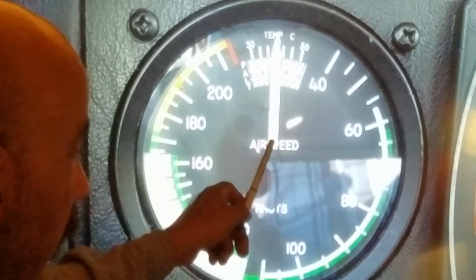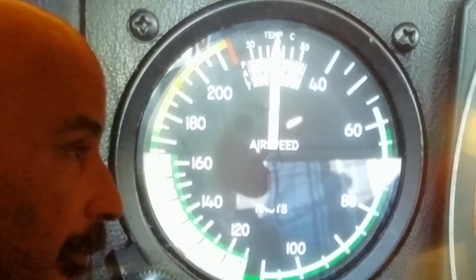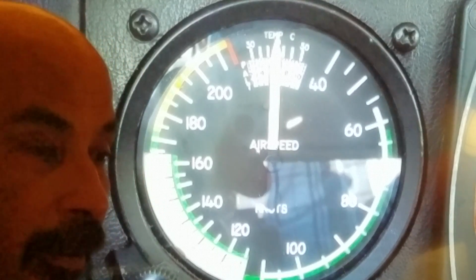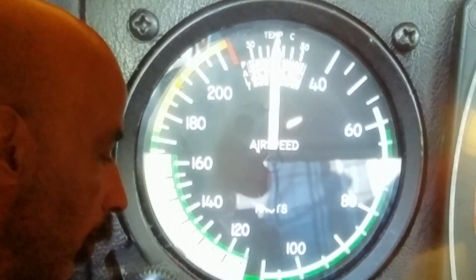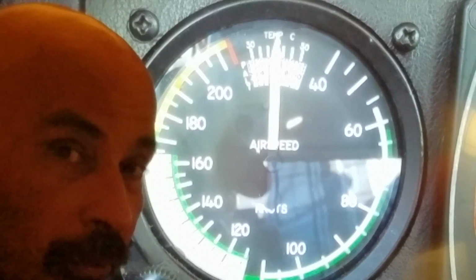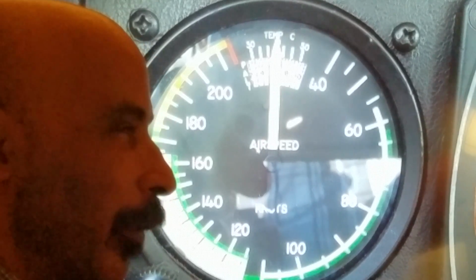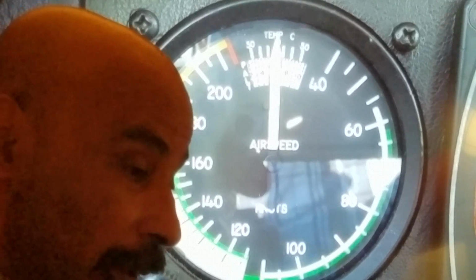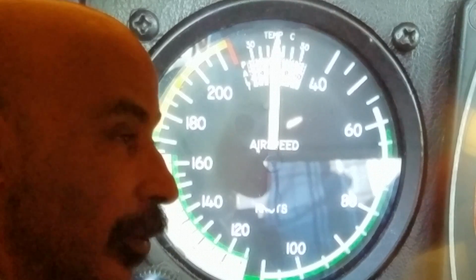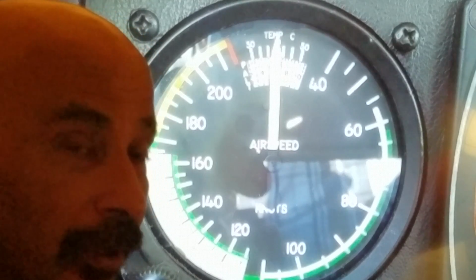And right now the gauge typically is reading 0. There is no airspeed. The aircraft is not moving. The sensor that is plumbed, connected to this gauge, is called the pitot tube, P-I-T-O-T. And I'll show you where it's located on the airplane eventually. You'll get very familiar with it. Evidently that is also a French word, P-I-T-O-T. We would say "pie-dot", but it's pronounced "pee-toe", although you will hear Americans say "pie-dot".